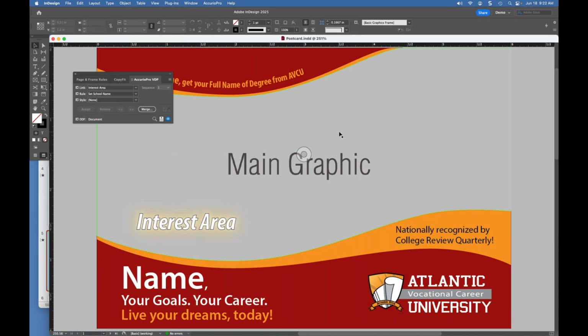Well, when you think about variable data in the context of InDesign, you need at least two things. You need the InDesign document, and you need the data file. Beyond that, you also need any variable graphics, any static graphics. You need the fonts. Maybe you need an imposition template. So there's a number of assets that you need to submit to Enfocus Switch in order for this to process a job. And collectively, those assets, we call that a package, a VDP package.